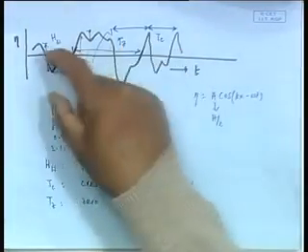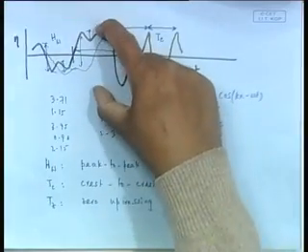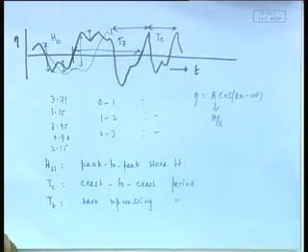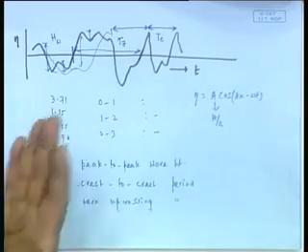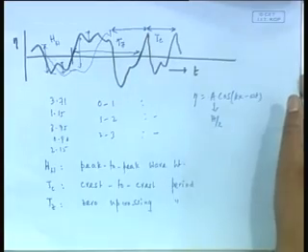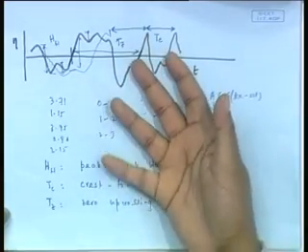For example, this signal, as I told you, I could stretch it keeping the height the same, and the analysis will give me the same histogram. You understand the point, that what I have done is only analyze the height. What about the quantities in this direction, that is length or period? We haven't done it. Now you can say, look, I can separately analyze Tz. That also people have done.